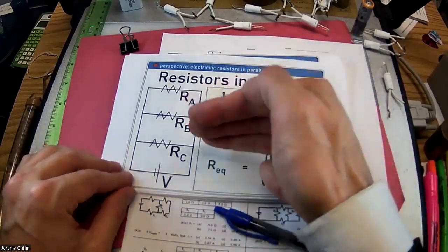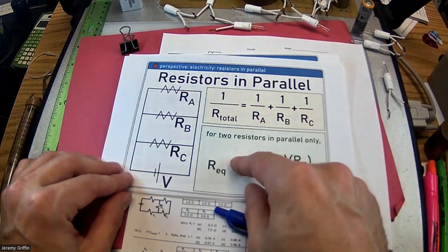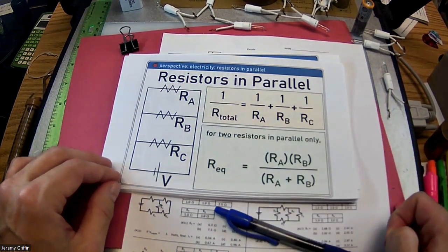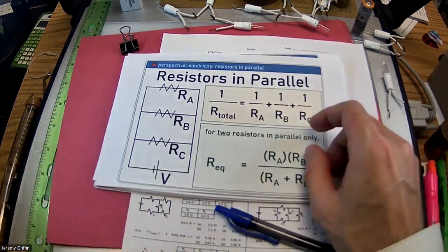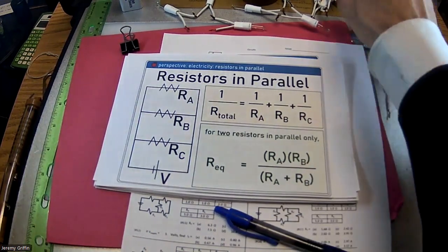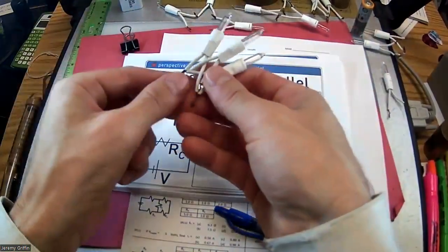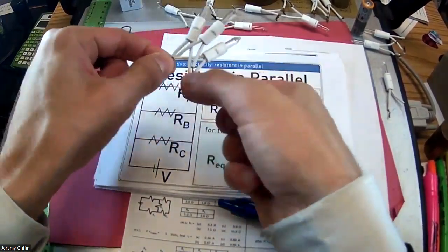Versus if you see resistors wired like rungs of a ladder, this is called in parallel. And the total resistance actually decreases when you wire them in parallel. Here's the math, how you do this. Let me show you guys what this looks like. These 3 guys are all tied in parallel because their leads are all tied together. Boom, boom, boom.